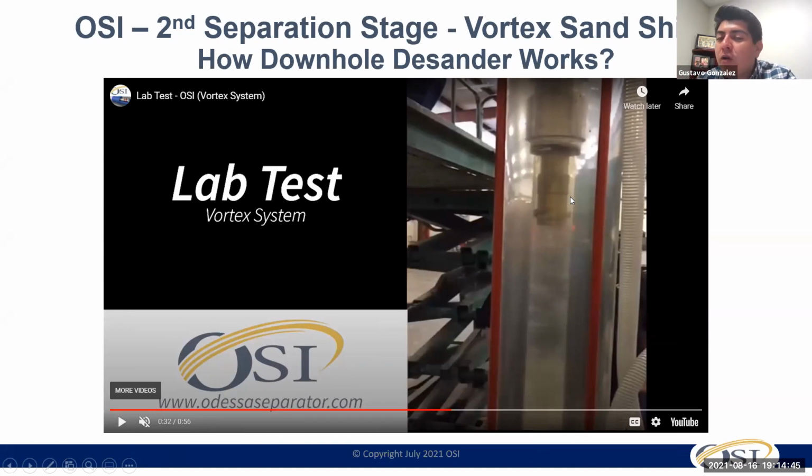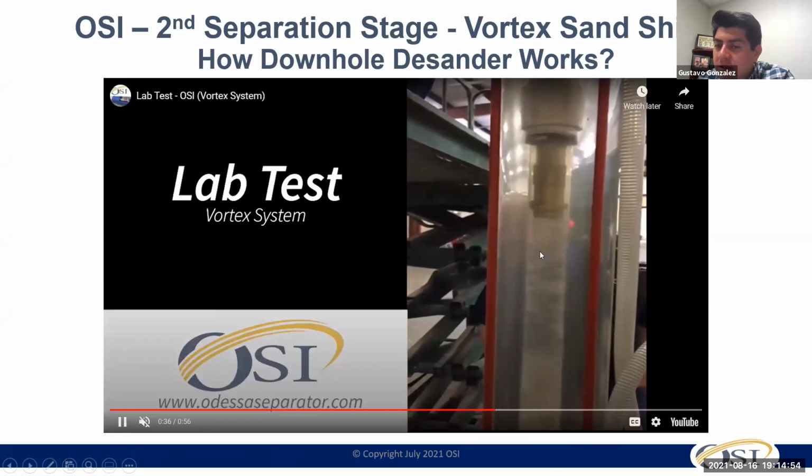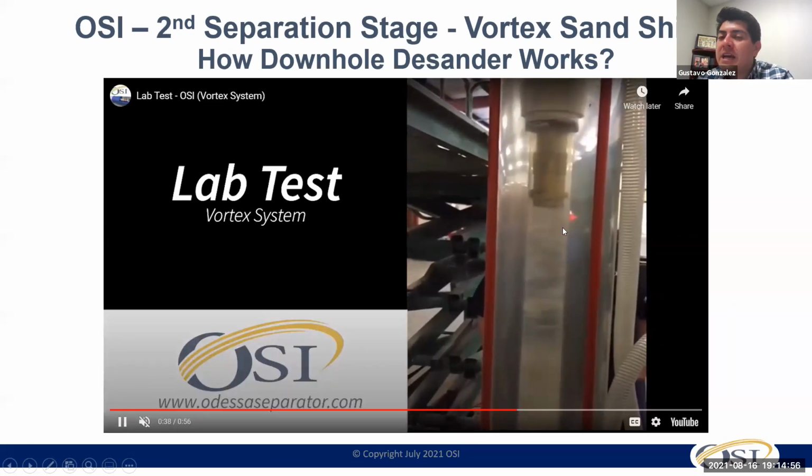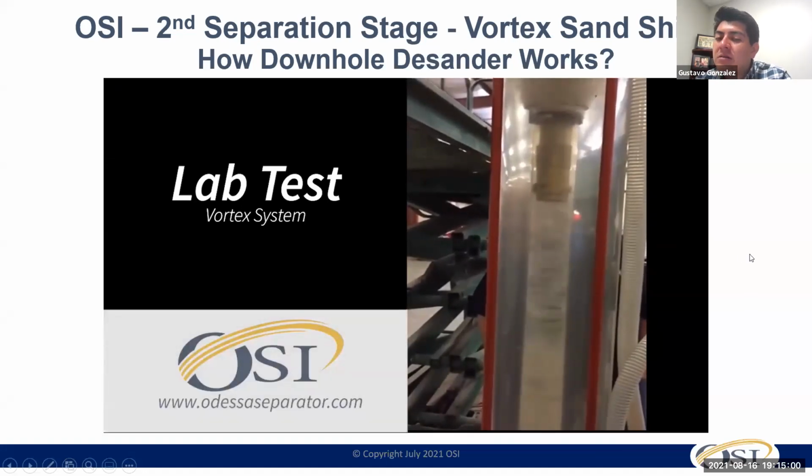That's why I have to take all those factors into consideration when I do my design, so I'm able to control this and return just fluid, with a lesser portion of sand, clean fluid through my pump, so that I'm able to actually handle the sand.